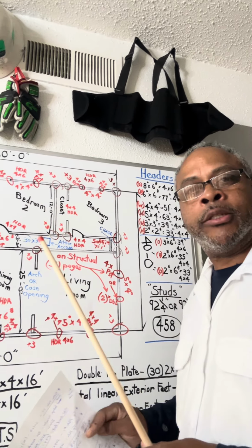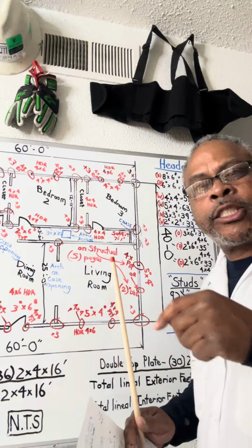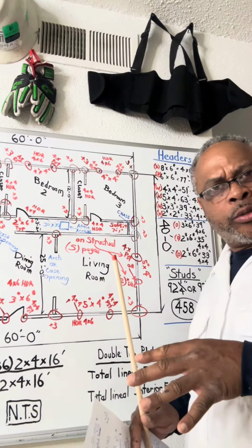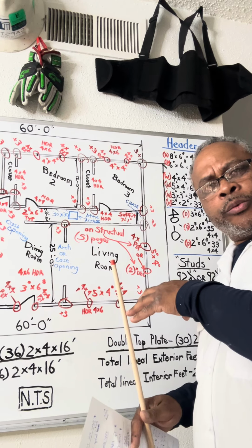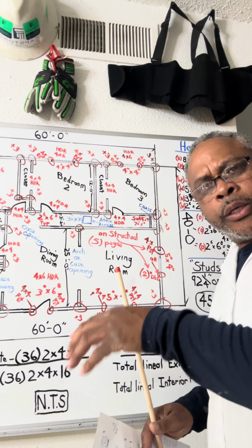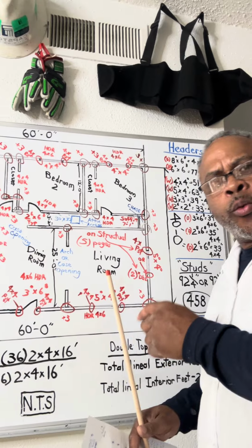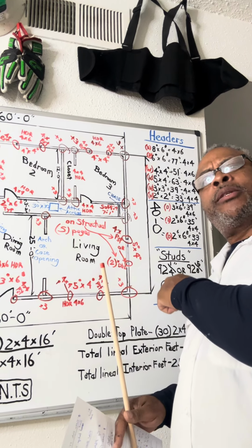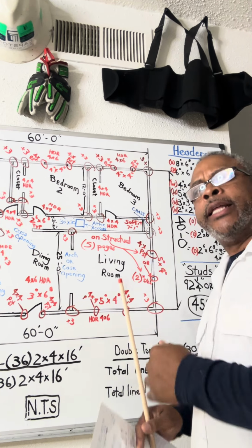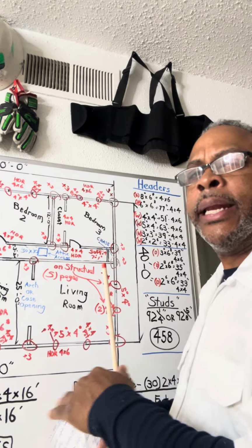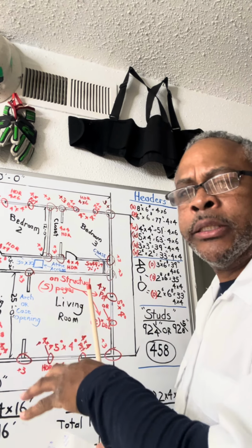And in certain parts of the country, you have to stitch nail the plate, about 20 nails on each side. The wall that you're plating over, you have to stitch nail that. Then the wall that you're coming from, that the plate is running from, stitch nail that. They want these walls stitch nailed, and they want a lot of nails tying both of these.